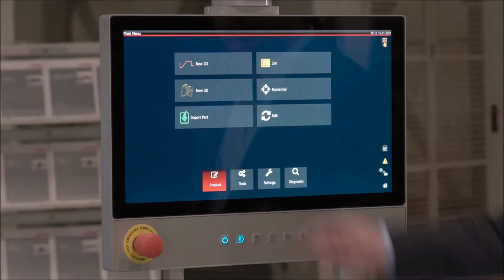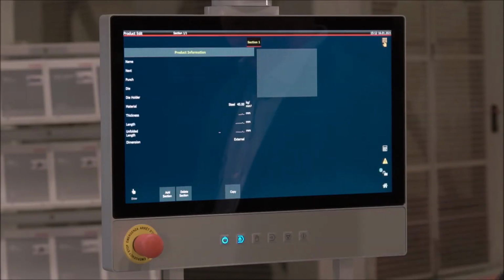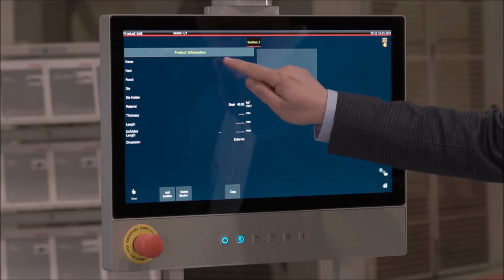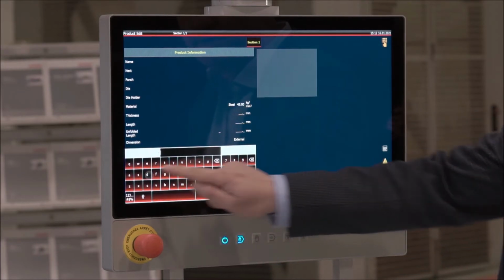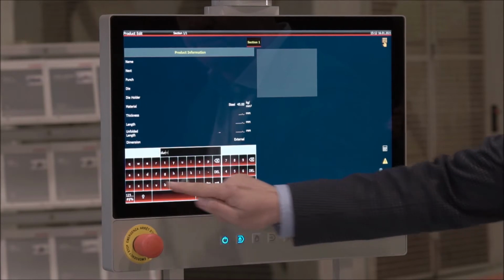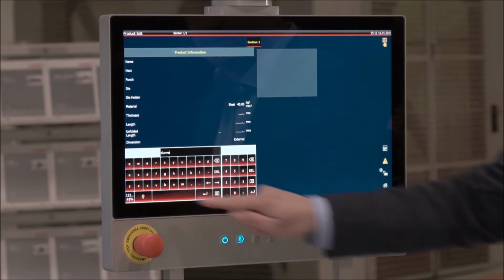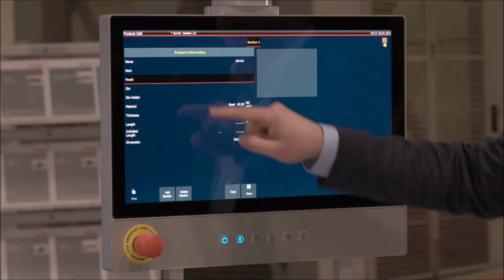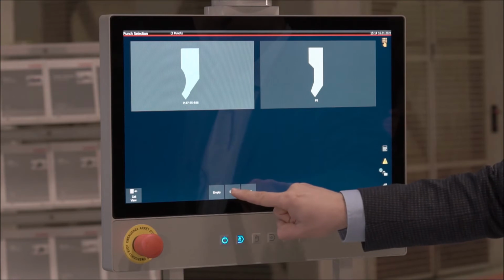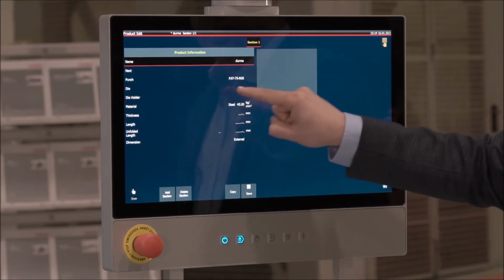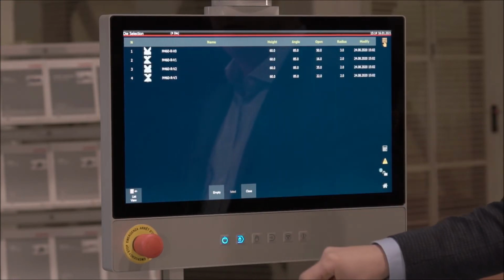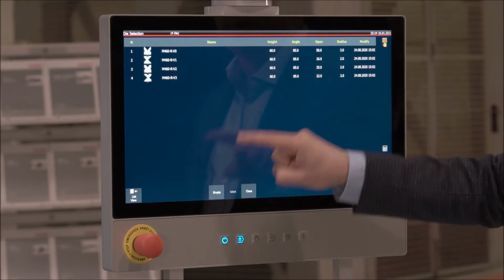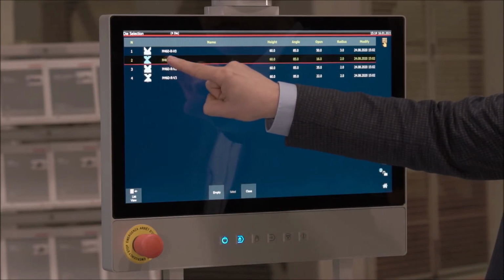We have two ways to prepare the bending: 2D and 3D programming. Let us start with 2D. First, we write the name of the program we will perform on the 2D programming page. Let's call it DURMA. We select the upper punch that we will use later in bending. Then we determine our die and we select the second tool since the die we will use today in bending is 16 channel.